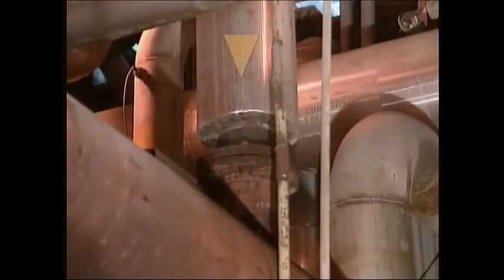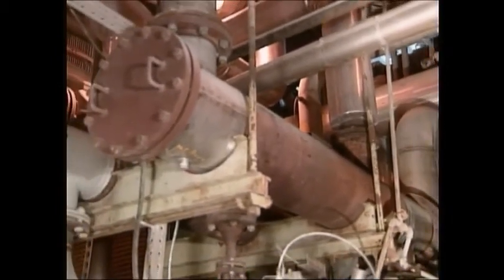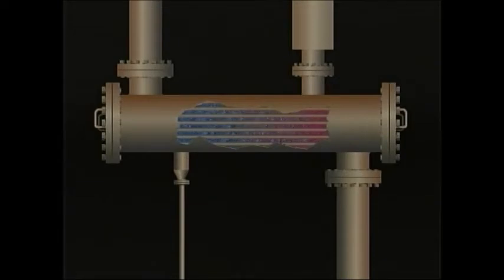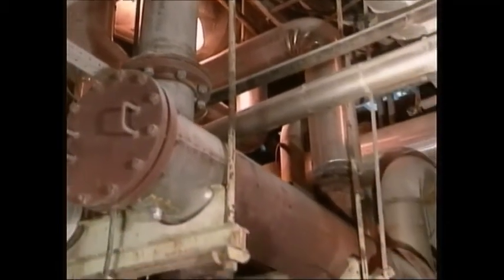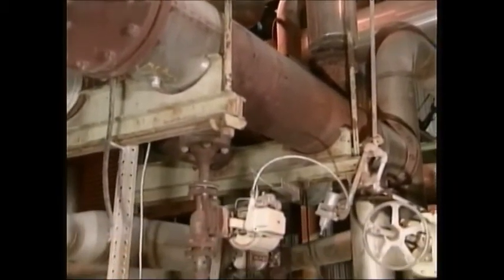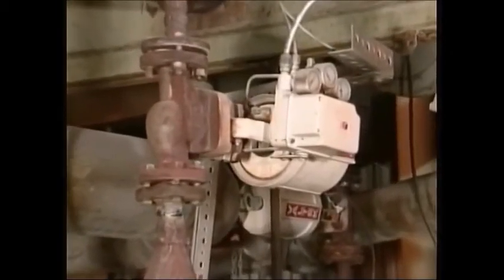System piping allows steam to enter the heat exchanger here. It then flows through the shell or outer housing. In the heat exchanger shell, the steam gives up its heat to increase the temperature of the second fluid, which flows through the tubes. The fluid to be heated by the process enters the heat exchanger here and passes through the tubes. After being heated in the tubes, it flows out of the heat exchanger. In this example, the temperature of the hot fluid leaving the heat exchanger is measured by a sensor. The control system controls the temperature by positioning this valve, which regulates the flow of the working fluid leaving the heat exchanger.